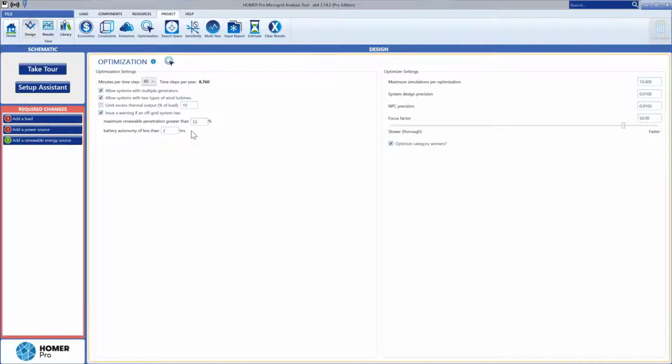If you're trying to push the limit on how much renewables you can put in with either a very small battery or no battery, you really do need to use one of these power engineering models that looks at transient stability. It's a totally different kind of model. It doesn't consider economics at all. It's just modeling the event. What happens if a generator goes offline really suddenly? The frequency is going to drop. You have a stability issue, and to a lesser extent, you can have the same problem, like we've been talking about, if a cloud passes over too quickly and you don't have any way to pick up that load. So if you have really large renewable penetration, you need to look at this transient stability issue.